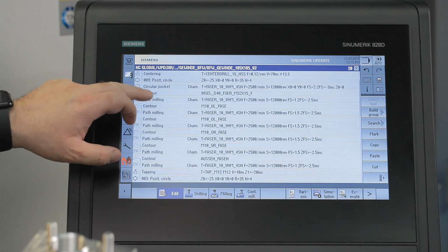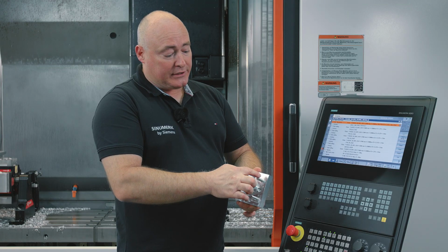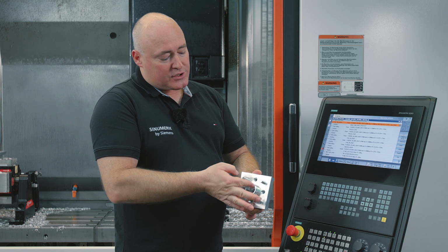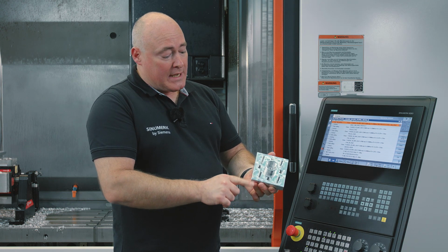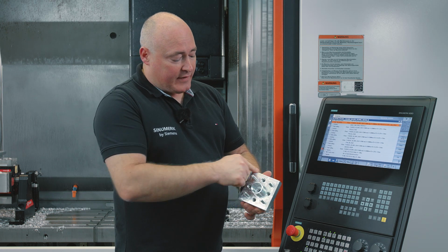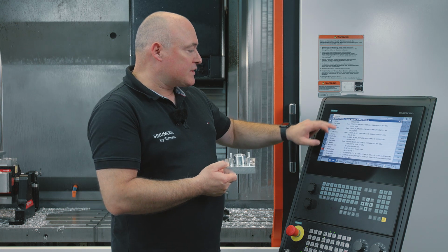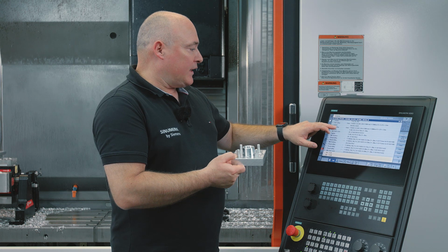And in precisely the same way as the chamfering on the tap hole diameters, the chamfering must also be done on the ridges, the future M10 threads, as well as on the M32 by 1.5 thread, and naturally on the outer edges of our workpiece. This is achieved by chamfering in milling mode with a 45-degree chamfering bit, which removes the sharp edges cleanly and completely.